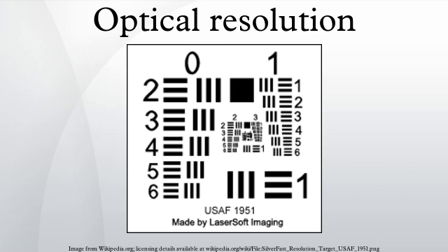To find a theoretical MTF curve for a sensor, it is necessary to know three characteristics of the sensor: the active sensing area, the area comprising the sensing area and the interconnection and support structures, and the total number of those areas. The total pixel count is almost always given. Sometimes the overall sensor dimensions are given, from which the real estate area can be calculated. Whether the real estate area is given or derived, if the active pixel area is not given, it may be derived from the real estate area and the fill factor, where fill factor is the ratio of the active area to the dedicated real estate area.